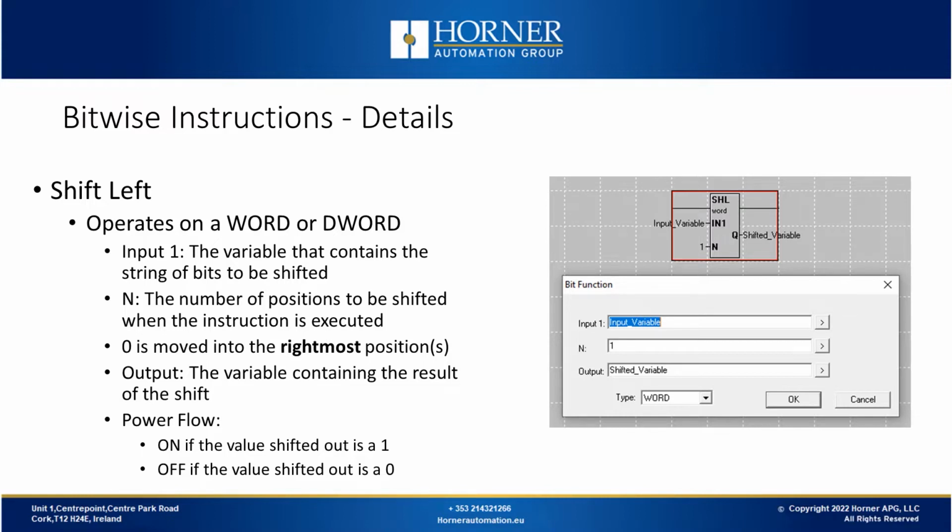Another question you may have is, does the shift left instruction pass power or not? Well, it does pass power if the bit that was shifted out of the leftmost position was a 1. If the bit shifted out of the leftmost position was a 0, then it doesn't pass power.